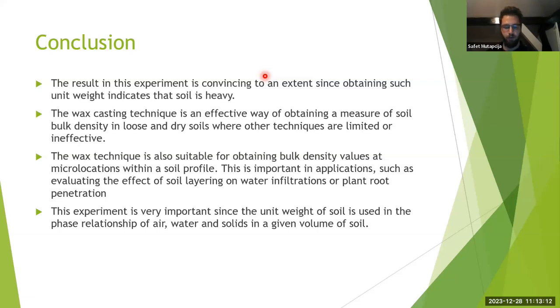One is the dynamical one, and one is a static one. What you usually have on site for quality control and quality assurance is mostly the dynamical one. European standards would say that you do one dynamical test on every 10 meters and one statical on every 100 meters of your road or your wall or whatever you're building. So in your design, you should specify a subgrade coefficient and the modulus of elasticity that needs to be reached. It's usually between 30 and 60 megapascals.